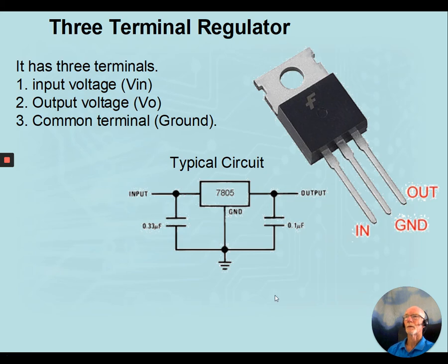The second type of voltage regulator we're going to be investigating on this course is called a 3-terminal regulator. It's called a 3-terminal regulator because it's got 3 terminals. Unlike a Zener diode or a resistor or a capacitor that's only got 2 legs, this one's got 3 legs. So its legs are its input, its output, and a ground terminal. And it's connected in a circuit like this.